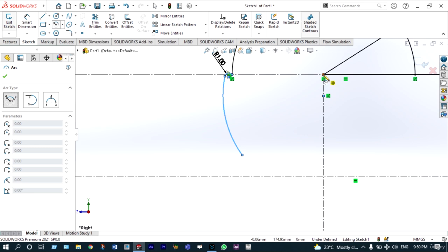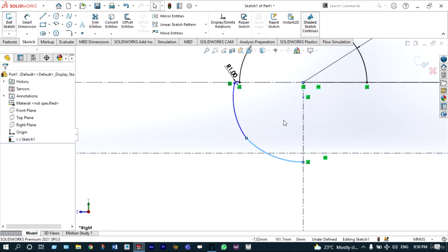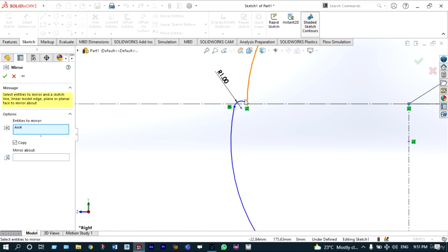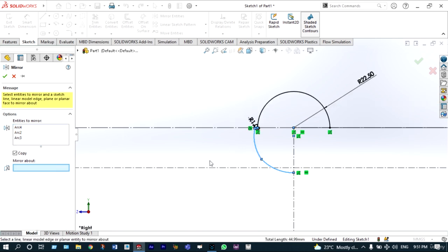And this part, circular section, should be added at this location. That can be initiated from the center itself. At this location, you have to provide a little bit of flat section. So we can provide these mirror entities at the right hand side. You can select that entities and that to be provided mirror with respect to that central axis. Done.